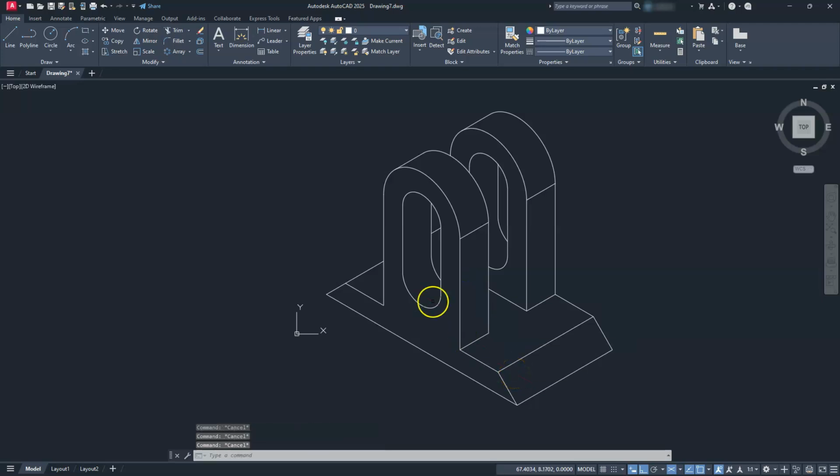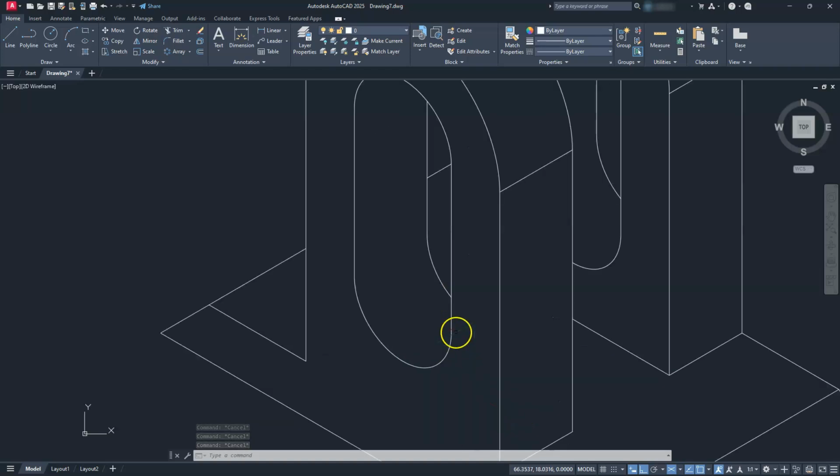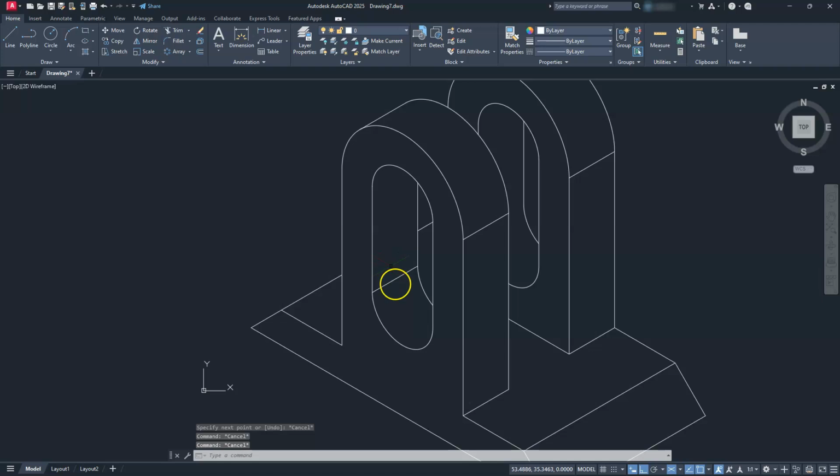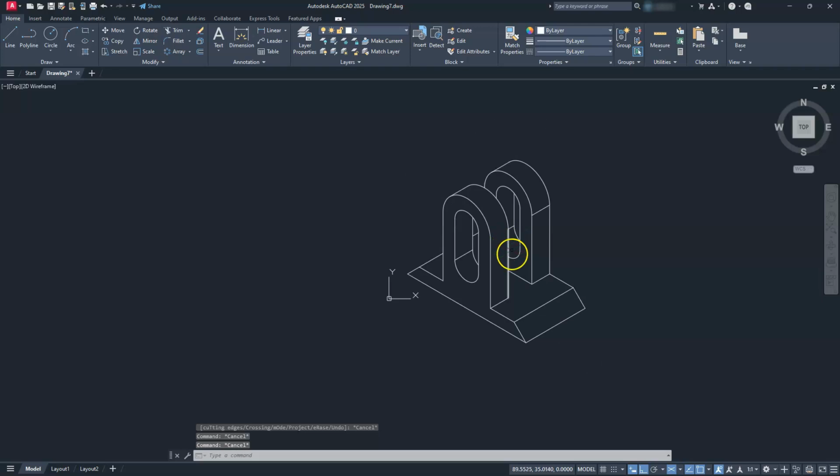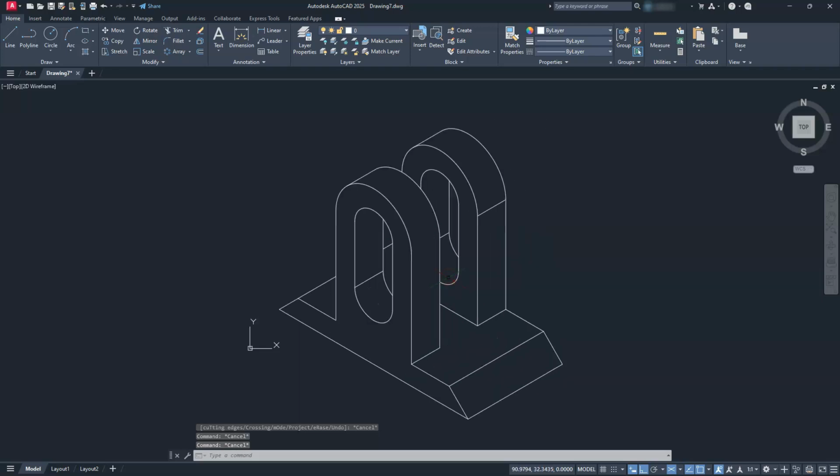I'm just kind of looking through here. Now there are some other contour lines that we can put on the inside of here just to show them. Like for here, I can draw a line from that endpoint going to this one. And that just shows a little bit more detail into that contour. Let's go ahead and copy this. Take it right to the back here at that endpoint. Then go back to the trim command. Alright, and I think I probably have this one done.